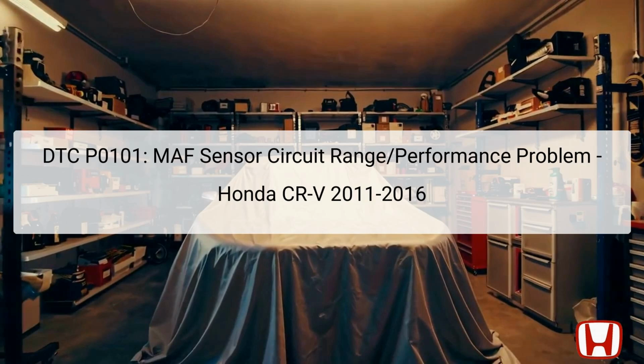When this DTC is triggered, it may indicate an issue with the performance of the MAF sensor or the overall air intake system. This code may appear with the Onboard Diagnostics 2, OBD2, and can affect engine performance, fuel efficiency, and emissions. Prior to troubleshooting, it's important to gather all relevant data, such as freeze frame data and any associated diagnostic pending codes. If other related DTCs are present, those should be addressed before focusing on P0101, as they may impact the MAF sensor's function.